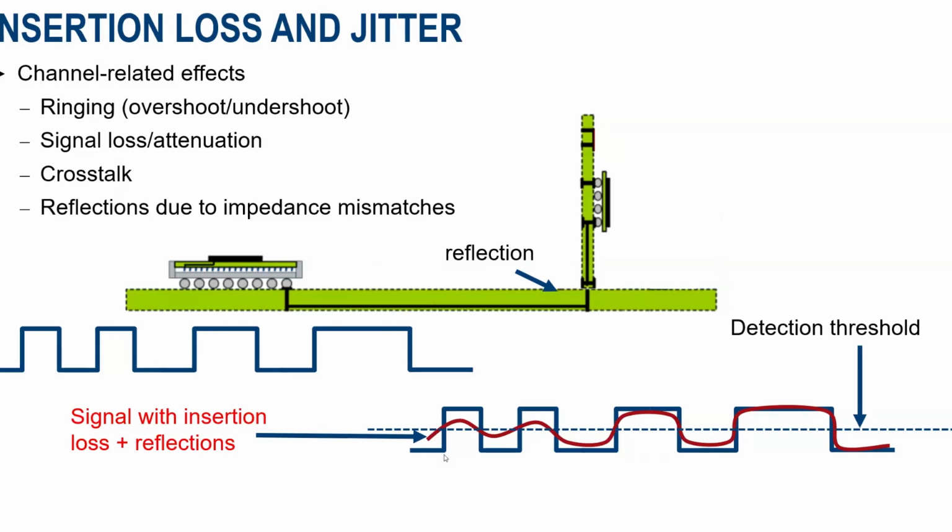And this is pretty common in most digital transmissions. Areas of the waveform where there is a lot of high-low transitions, like, for example, a 1-0 data pattern, you're going to get a little bit more attenuation there and some phase shift compared to areas where you might have a string of 1s or 0s where the signal level doesn't change. In that section, you might have less loss and, again, less phase shift as well.